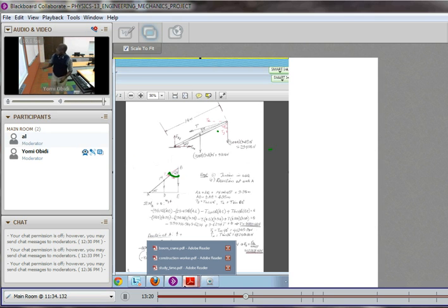So we also know that the weight of the boom is acting at its center of mass. This is known because we know the entire length. That means this entire length is 14 meters. From here to here is necessarily going to be 7 meters. It's halfway. So with that information, we re-represent that here. This is primarily for the geometry, whereas this is for the forces in play.